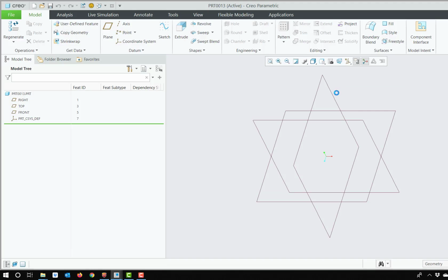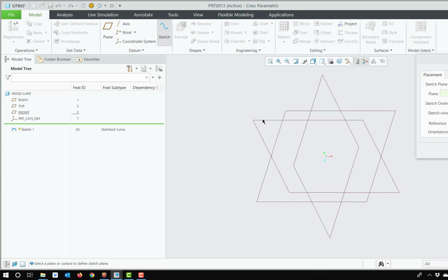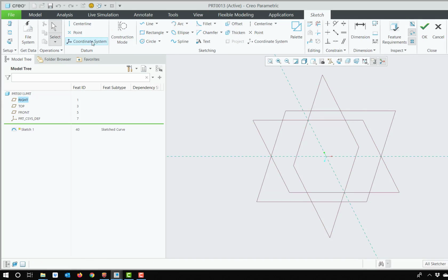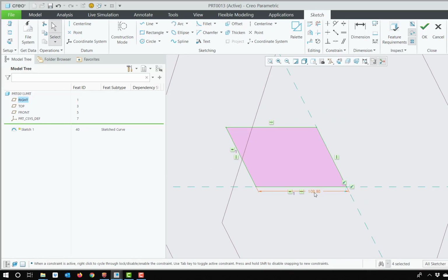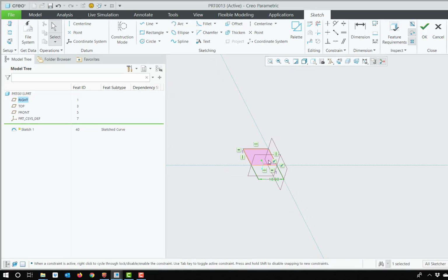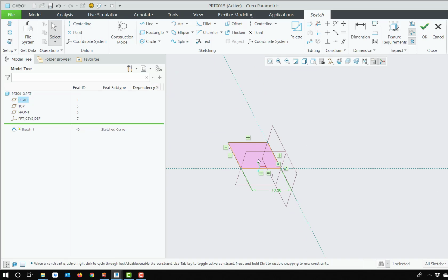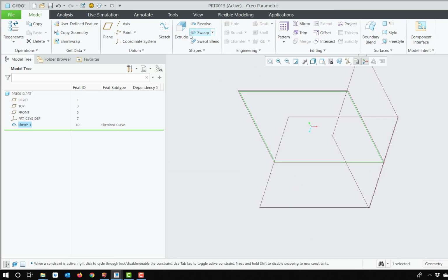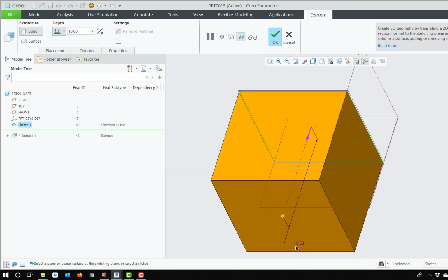build a part here, want to build a sketch. So you place the sketch on that plane. I'm going to draw a simple rectangle, and it gives us our default value here, actually a square. I'm going to set that to 10. Okay, with that value of 10 being the only value it really has to calculate with, when I hit OK and tell it to extrude, notice the extrusion length is set to 10 automatically.